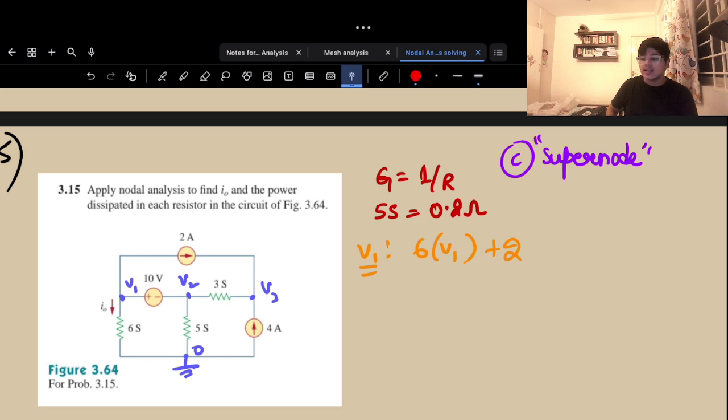So that's why you need something called a supernode. Now the statement of KCL, that the net current, that's the algebraic sum of the current entering or leaving a particular closed region, is zero, comes into a lot of use here. Now I can consider this particular region as a closed system. And for this closed system, I can still apply sigma I is equal to zero. It is still valid because the theorem literally states that it should just be a closed area, closed region.